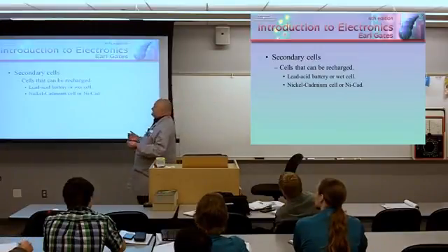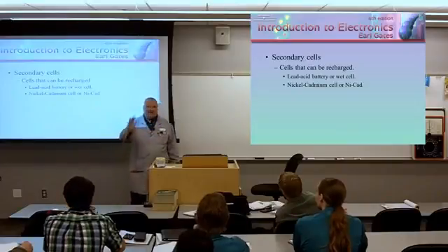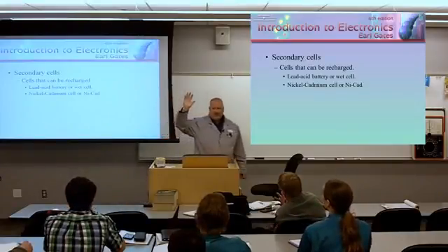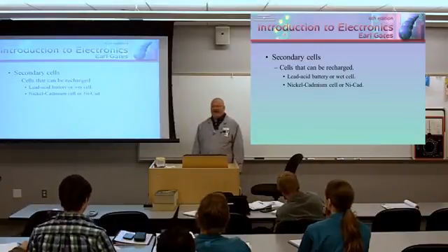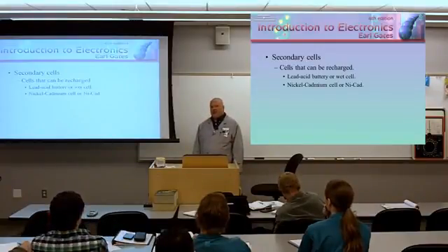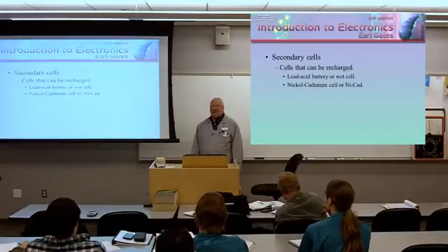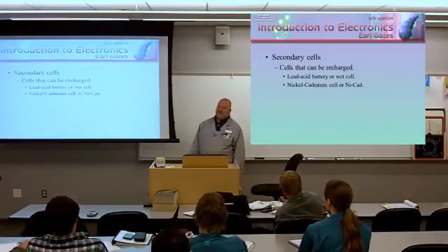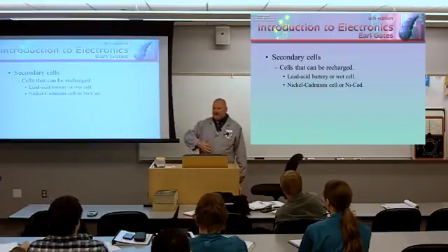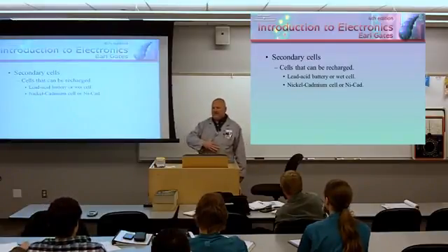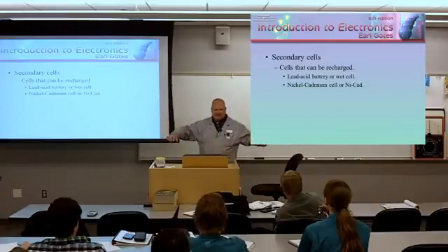Now, you're all familiar with lead acid, nickel cadmium, NiCad. How many of you are familiar with NiCad batteries? NiCads have been out for a long period of time. NiCads had a nasty habit of generating what was called a memory. And what that memory was, in essence, is if any of you have ever had your arm or leg in a cast and you don't use it, basically the muscles forget how to fully exercise your range of motion.